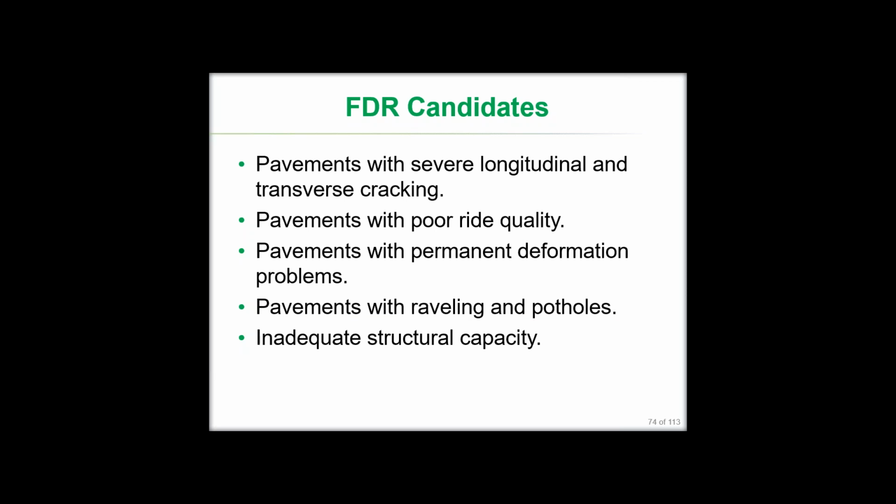The applicable or the best candidates for FDR applications are pavements with severe longitudinal and transverse cracking, pavements with poor ride quality, pavements with permanent deformation problems, pavements with raveling and potholes, and inadequate structural capacity. So we can use FDR pretty much for pavements in severely deteriorated condition.